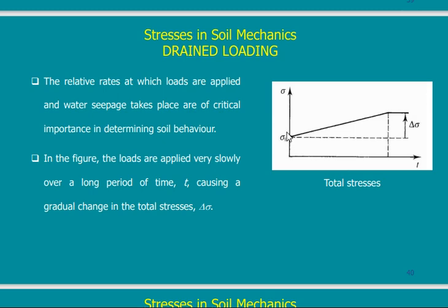So the first graph just shows me that I started with a certain stress, and then this stress increased. Suppose I'm standing on the ground, then here will be my own weight. And then every time you give me something to carry, my weight is going to increase. If you give me 1 kilo, then my weight will increase by 1 kilo. Then you give me 10 kilos, my weight will increase by 10 kilos. So as time passes, your weight is going to increase till you reach the maximum that you can carry, and then nothing will happen again. So this is the first graph showing the relation between the total stress, which is the total weight on the soil, compared to the time.